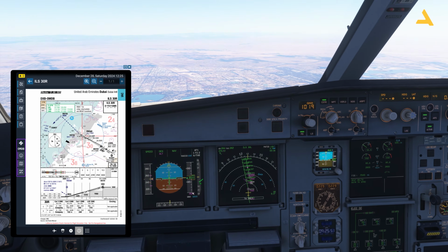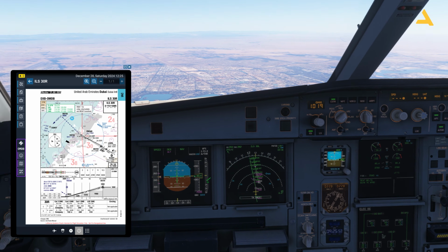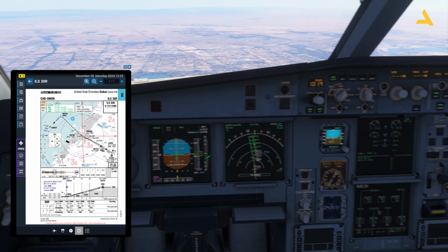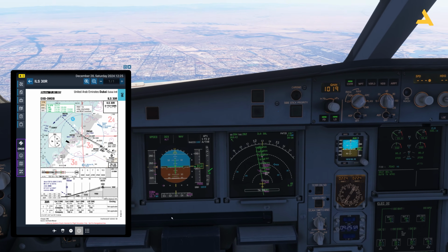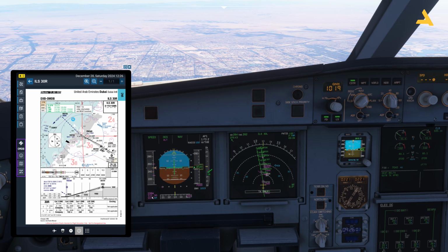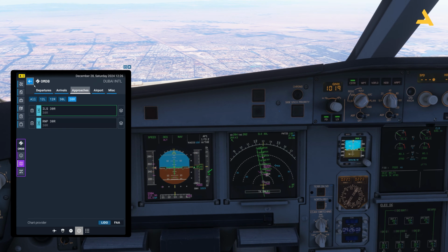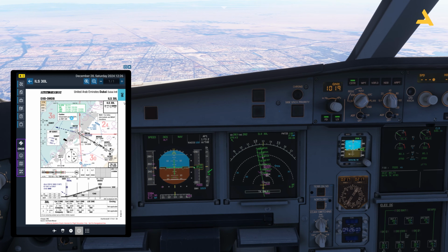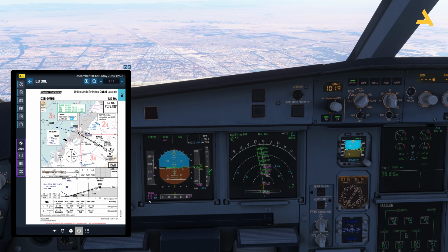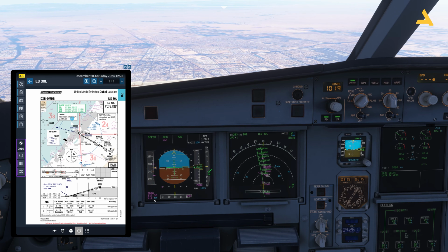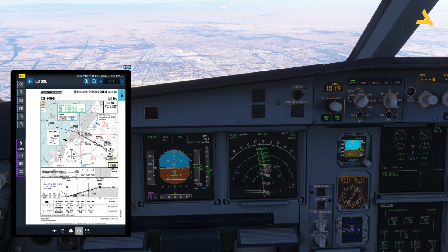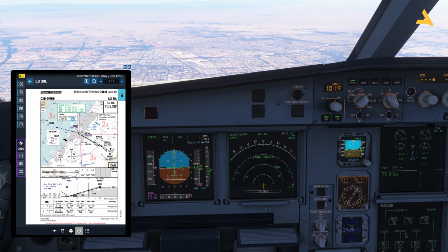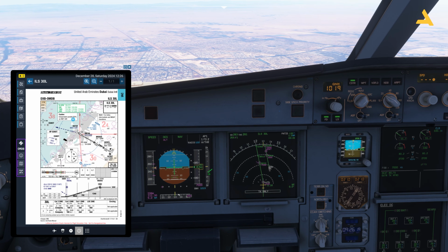And now I will be going for the autoland. So I will now turn on the ILS, and it will start to show me the frequency of the localizer. Let's go back, 30 left, select this, and the distance to it. Right now the distance is not correct, obviously, as I'm going to cross this runway. I will go to this point and then come back and land. But it's good, it's here.